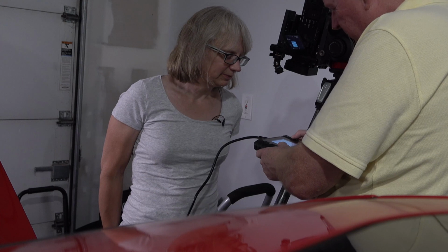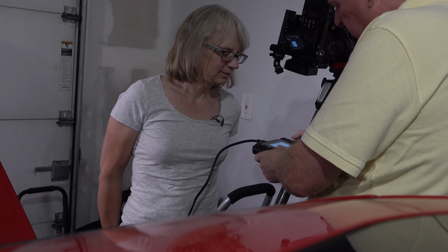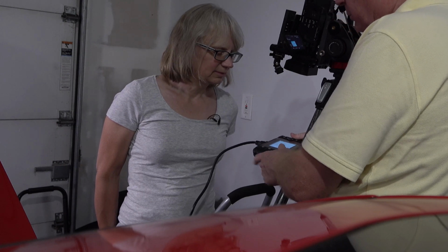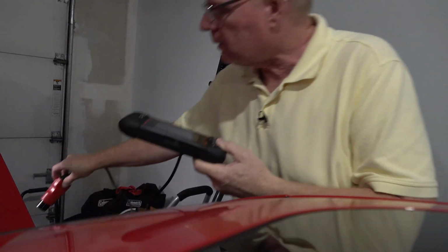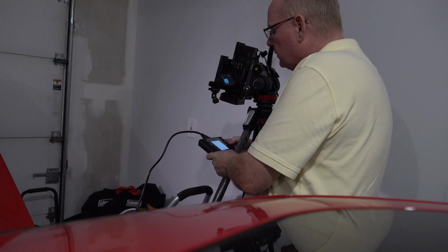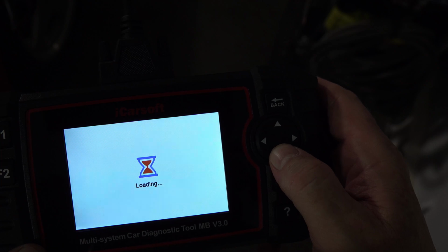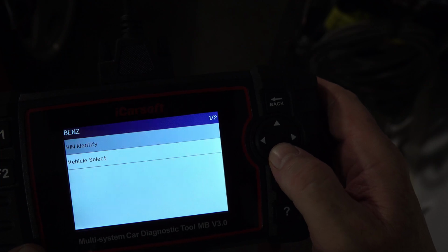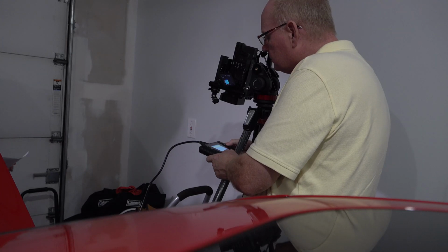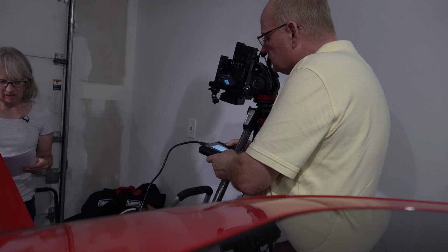All right, so let's see. I think we did everything we could do. So let's go try to save the data before we reset any other codes. I'm gonna put it back in. Okay, Di, I'm gonna reset your fault codes, all right? Once you reset it, the check engine light may come off? I don't know. We're gonna find out. But I like this. Transmission oil temperature sensor. Resistance too low.